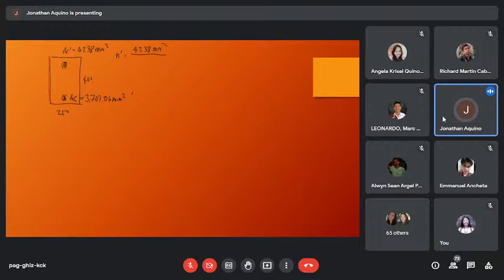divided by the area of 25 millimeter diameter bars. So N is 4238 divided by pi over 4 times 25 squared. So this will give 8.63. Okay, so say 9 diameter 25 mm.